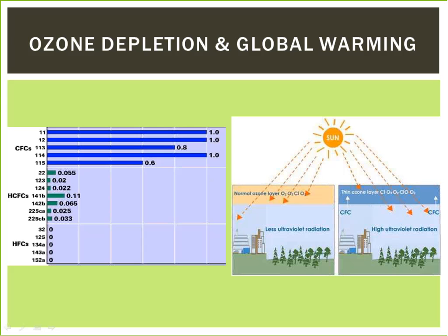Halocarbon refrigerants typically have higher GWPs than carbon dioxide, but are in much smaller quantities. The GWP of a refrigerant does not in itself exclude it from use, but should be considered when evaluating it. Of greater importance is TEWI, or total equivalent warming impact.